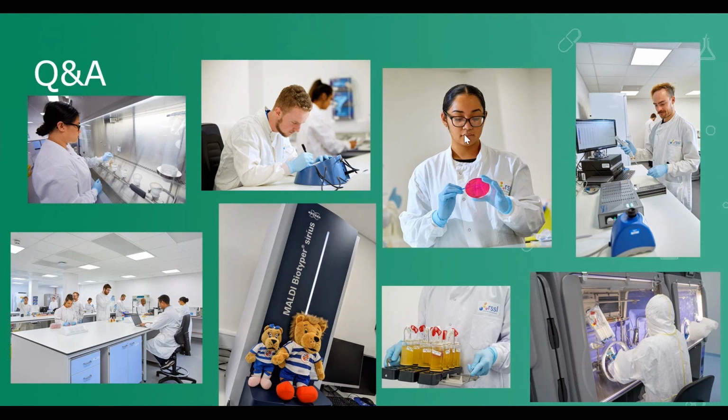And I think the first ones that come along will be the evolution of the spectrophotometric counters, which can differentiate between non-viable and viable particles, so they're more likely to come online. It's always a grey area. I do remember one MHRA inspector saying to me how they define the C before GMP, the current GMP, and it's sort of once we've seen something in 50% of the places we've inspected, it then edges much more into what suddenly becomes expected in more places. So it's an evolutionary concept.